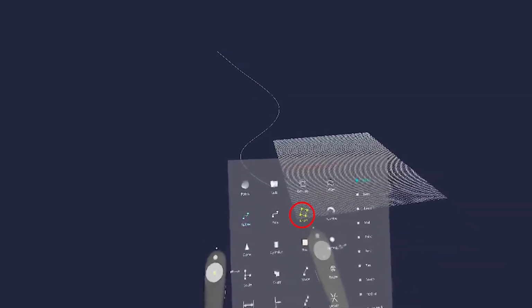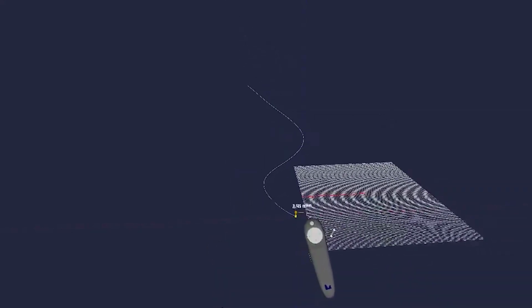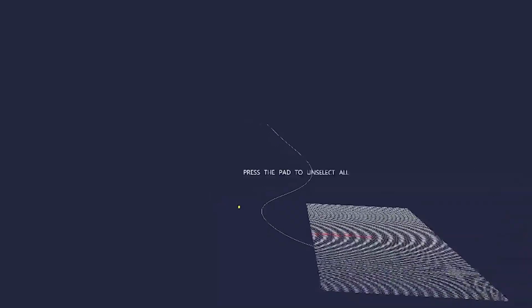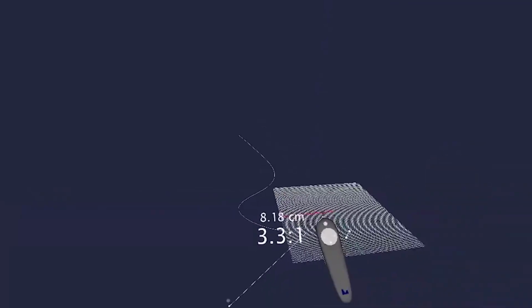Next, let's turn on the knots and adjust the spline to a shape that we'd like to revolve around. By clicking the point and selecting the move command, you can start to adjust the spline. Try to keep the line in plane as well. But after you've adjusted the knots, twist around and make sure the line is still planar.